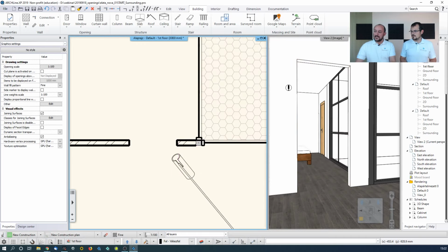It's actually just making an opening here. It's very good for open spaces. Now, in case you have 2 rooms separated with a wall and with an opening here with a lintel on top, this is what you will use. In case there is actually no opening, there are just 2 walls having a gap between, then you can just model it with 2 walls with a break inside. But in case you have a lintel at the top of the opening, you will use the door or a window perhaps.